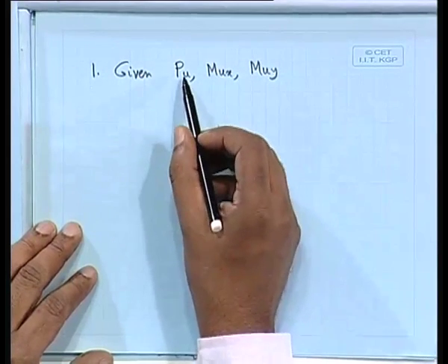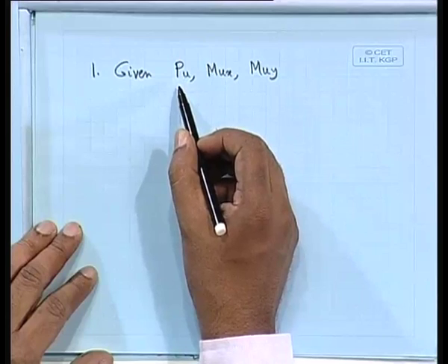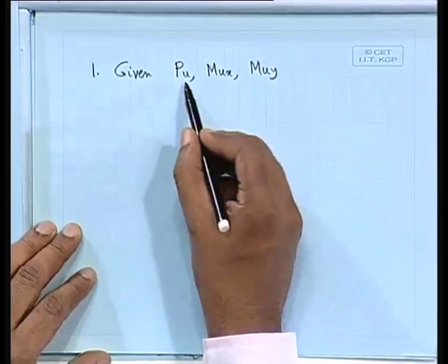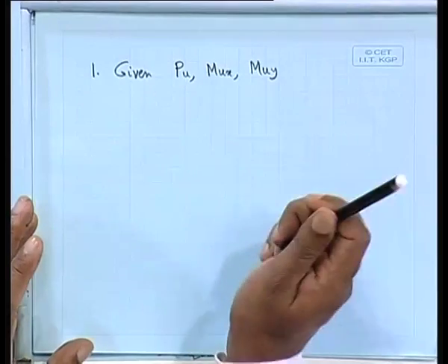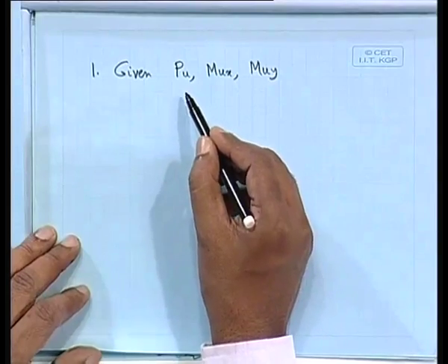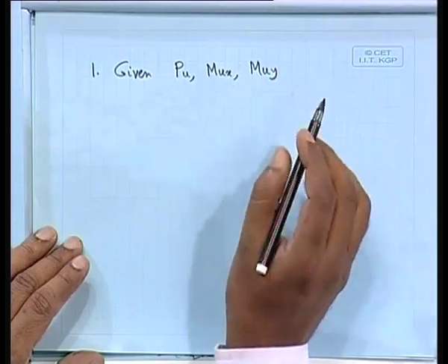Please note, we are talking about design load. Generally it happens that P is coming from the top, bending moment also coming at the column junction, P also coming, the actual load. Now, after multiplication by 1.5, all those things, including the self weight of the column also you have to take, finally it is coming as a Pu. Okay. So, Mux, Muy, all those things, whatever way it is coming.